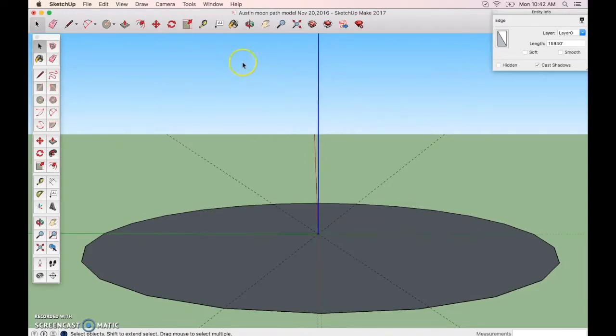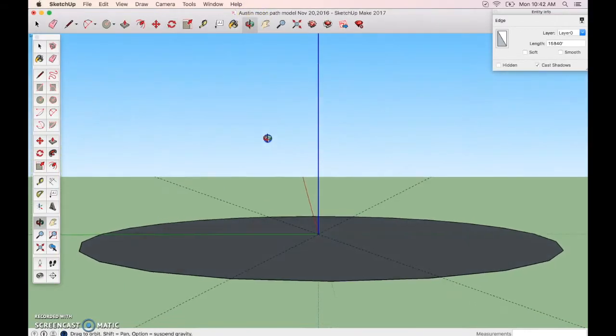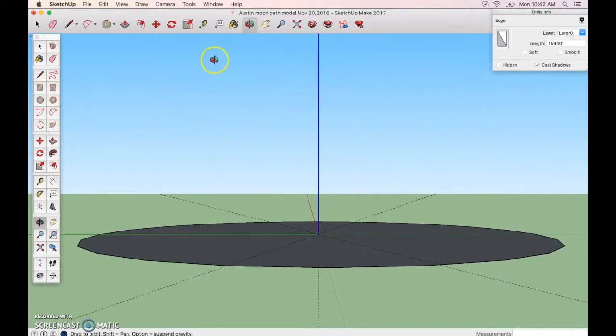the line is selected. We're going to grab the rotate tool. We're going to bring it down here. It looks like a protractor. Now if it lays down flat like that, what you need to do is take this and rotate it a little bit flatter. And now it's going to stay vertical. We're at the end point, so we're going to click there. We're going to come up here on our line, click again, and now when we drag it, it's going to move the line along the plane of that green, the north and south.